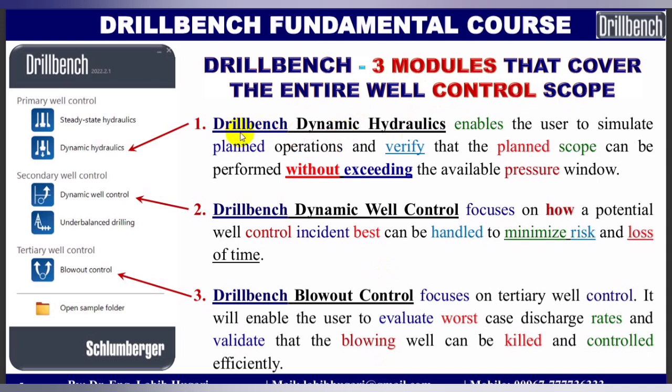Drillbench has 3 models that cover the entire well control scope: Drillbench dynamic hydraulics, Drillbench dynamic well control, and Drillbench blowout control. The first one, Drillbench dynamic hydraulics, enables the user to simulate planned operations and verify that the planned scope can be performed without exceeding the available pressure window.